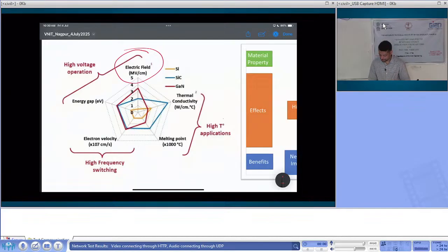In addition, there is high thermal conductivity. What it means is if your device is switching, I square R losses are happening, switching losses are happening, the heat has to come out, and as the heat comes out, it will create a temperature difference. If heat flows through a pipe, it's like an electrical circuit. The difference in temperature is the same as difference in voltage, and therefore the larger the heat flow, the more the temperature difference.